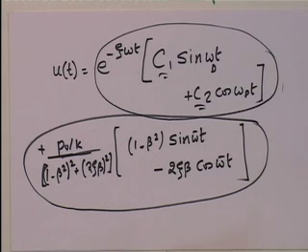So, in other words, the response of a single degree of freedom system depends on zeta and omega, which are the dynamic characteristics of the structure, which we talked about two lectures ago, and the ratio of the excitation frequency to the natural frequency.